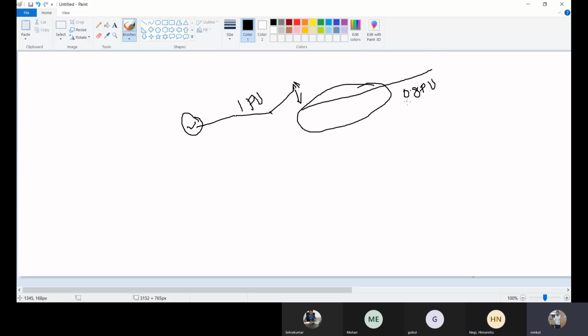But to get a worst condition, we have to assume there is about 1 per unit amount of trapped charges on this side. Now when we perform this disconnector action, this 1 per unit voltage and this minus 1 per unit voltage will come to this location.